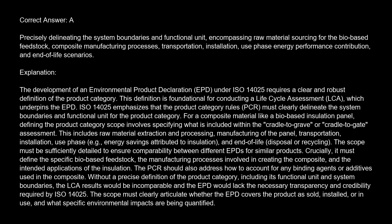Crucially, it must define the specific bio-based feedstock, the manufacturing processes involved in creating the composite, and the intended applications of the insulation. The PCR should also address how to account for any binding agents or additives used in the composite. Without a precise definition of the product category, including its functional unit and system boundaries, the LCA results would be incomparable, and the EPD would lack the necessary transparency and credibility required by ISO 14025. The scope must clearly articulate whether the EPD covers the product as sold, installed, or in use, and what specific environmental impacts are being quantified.